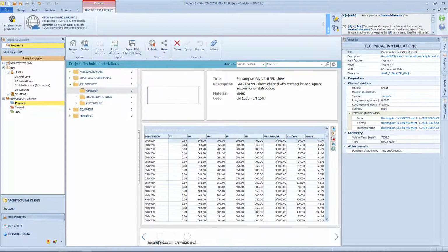Some parameters such as thickness, internal or external diameter, base, and internal or external height for rectangular shapes are interdependent. When one of these parameters is changed, the others will automatically adjust their values. From these parameters, the surface of the internal section is automatically obtained. This is a non-modifiable parameter. Same for the value of the mass of the pipe, calculated by the software starting from the dimensions set. And for the value assumed by the density, shown in the properties toolbox and related to the material used.